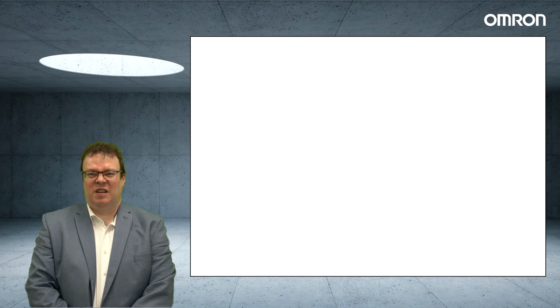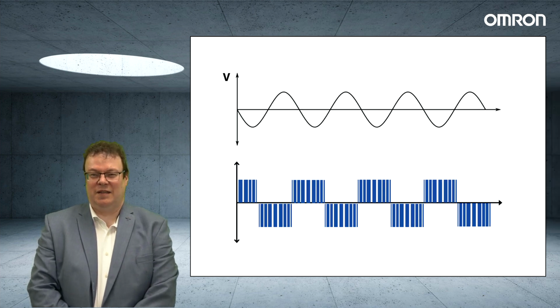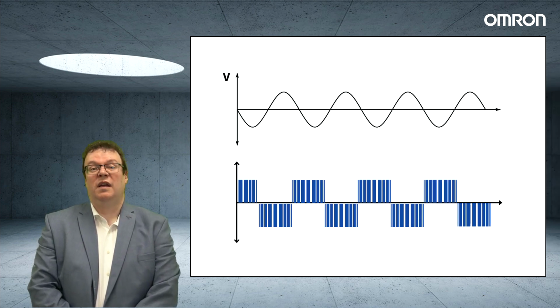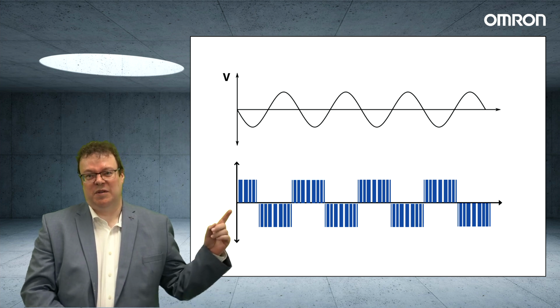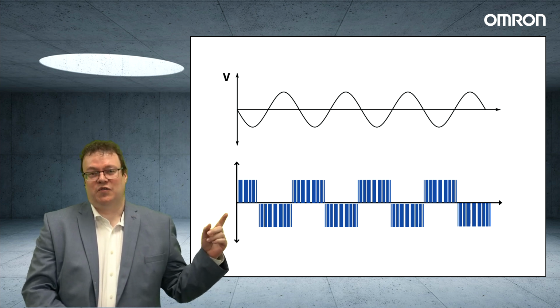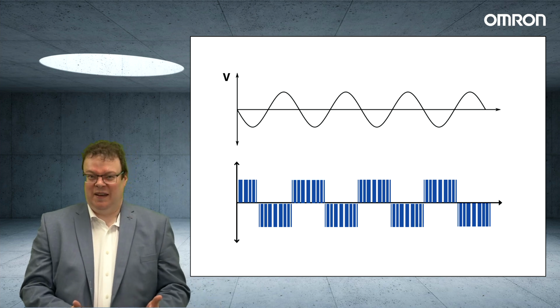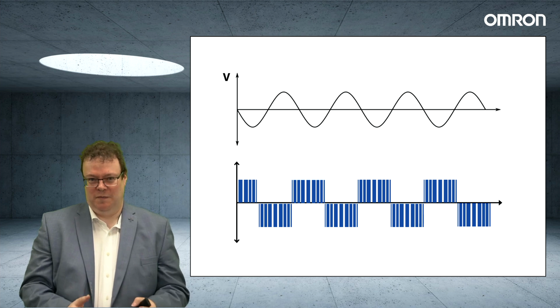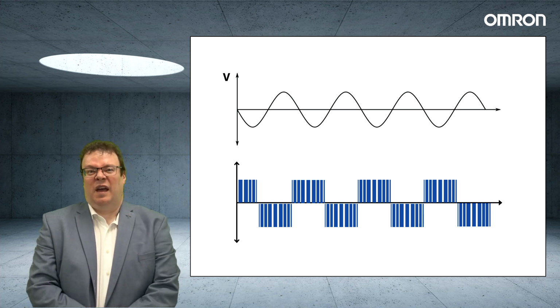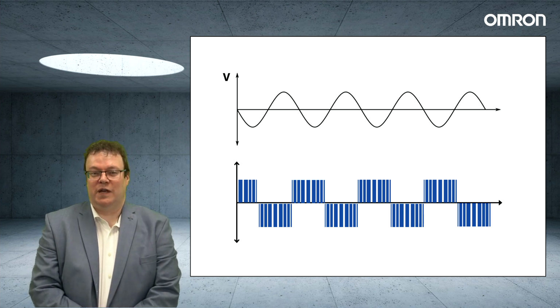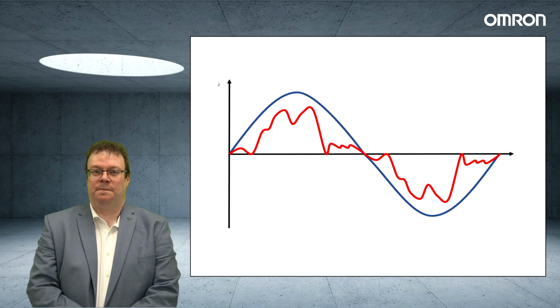We've also discussed in the talk how an inverter drive operates using pulse width modulation. So essentially the inverter is creating a series of pulsed square waves using a transistor. This is seen as a sine wave by the motor, as it's simply a large coil on the rotor and the stator. This allows you to vary the amplitude and the frequency and control the speed of the motor.